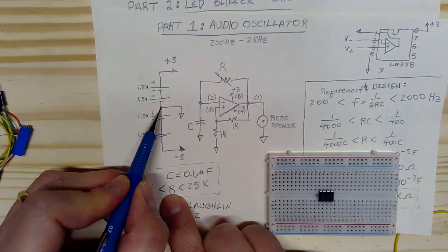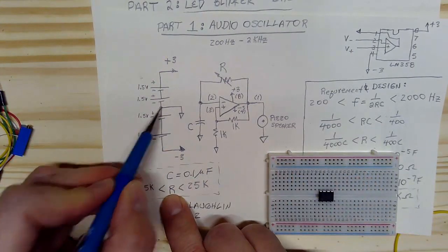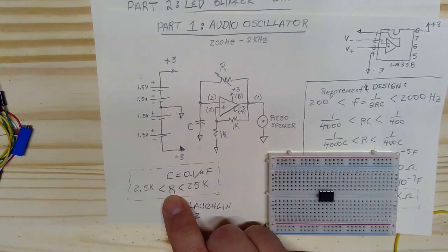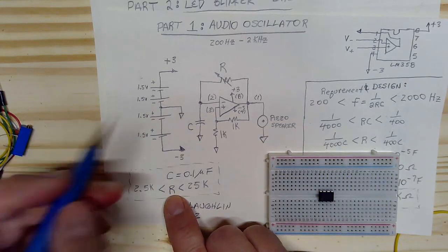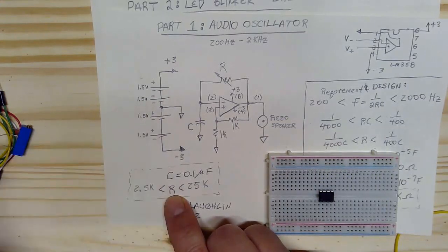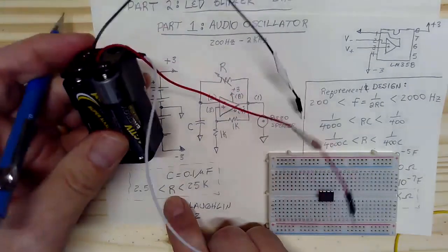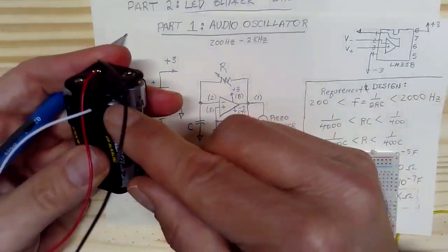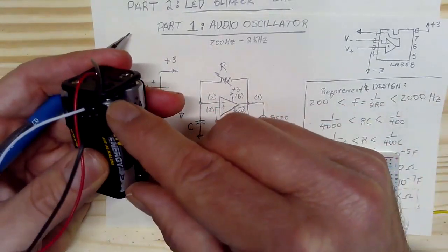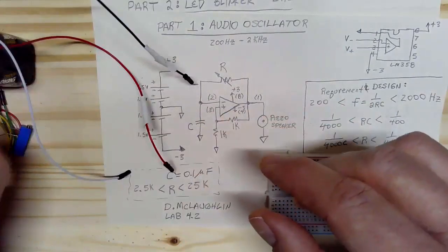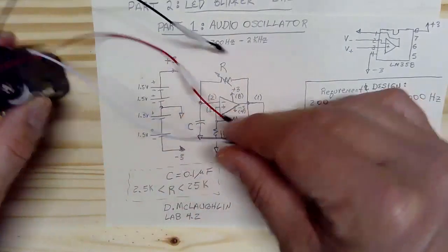What you need to do is find the point, and you can do this by just observing the battery pack, or you can use a multimeter. You want to find this middle node on here, and you want to just shove a wire in there, like I've done here. I've just taken one of our little wires and shoved it in there, and I'm going to use that wire as our ground.